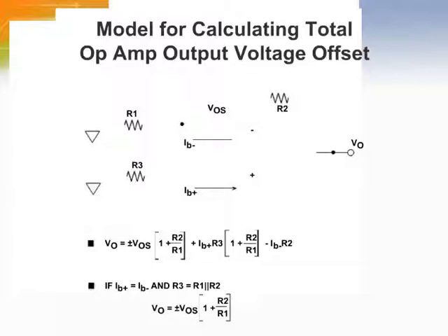High-speed op-amps are optimized for bandwidth and settling time, and not for precision DC characteristics as found in low-frequency op-amps. High-speed op-amps do have reasonably good DC performance. The model shows how to reflect the input offset voltage and the offset currents to the output.